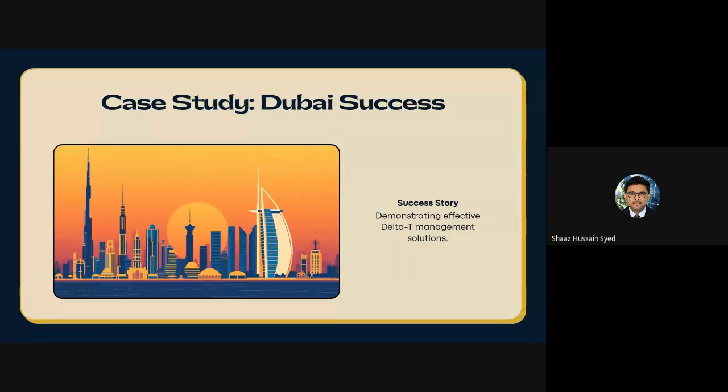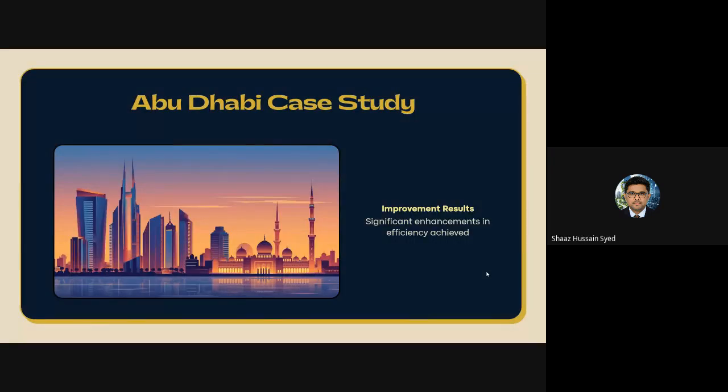Okay. And now let's move on to the next slide. The same issue we faced in a retail complex in Abu Dhabi. We had one project where the tenants were complaining that the AHU was sweating, with high humidity. The issue was that the filters were not clean, no discharge temperature control was there, and again we had an issue with the bypass valves, which were fully open in this facility.